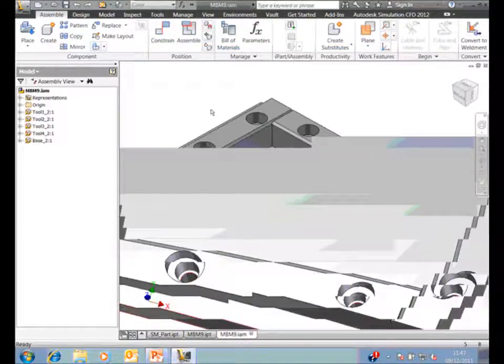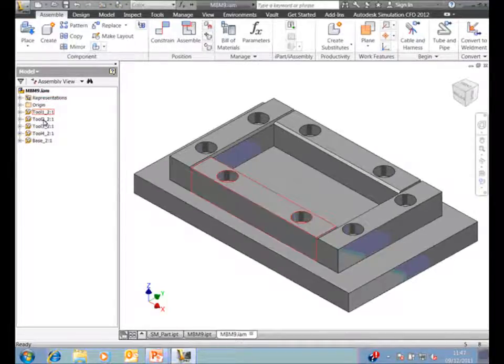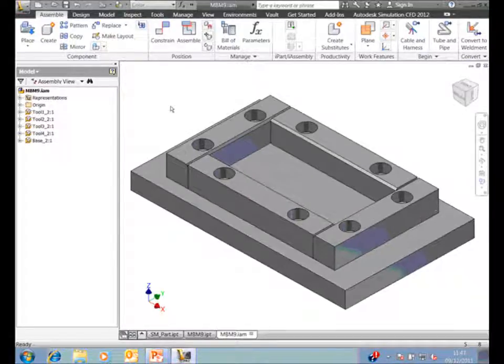with all our parts in this time. So we're now in an assembly file with all the bodies converted to part files, with a push pin on everybody, because of course you don't have to assemble this. The assembly is actually done within the part file. The part file decides where everything is placed, so you don't actually have to assemble anything. There's nothing to stop you ungrounding these and reassembling them should you wish.